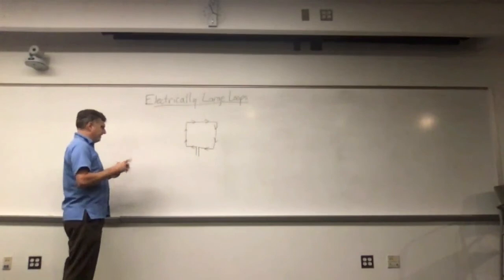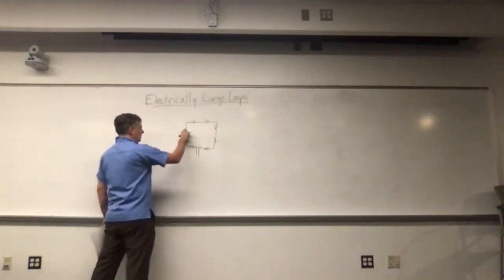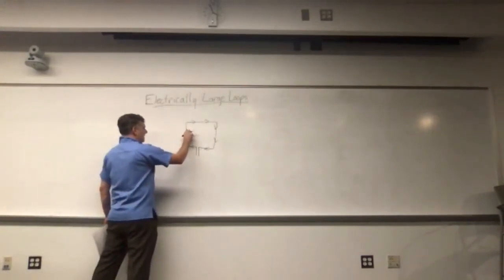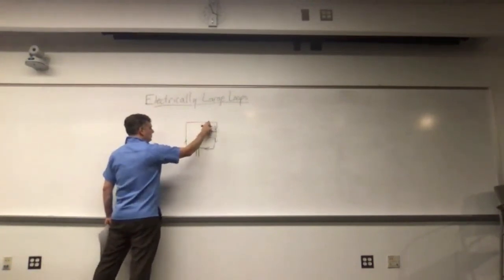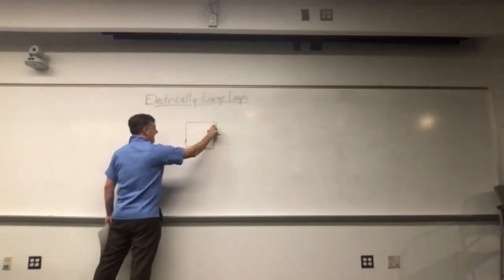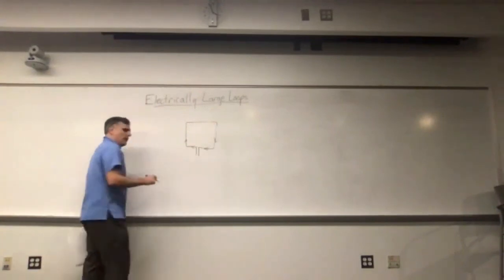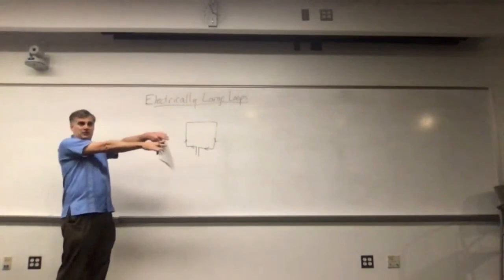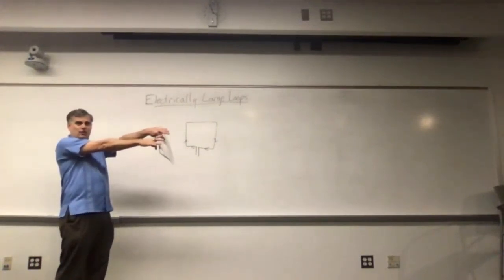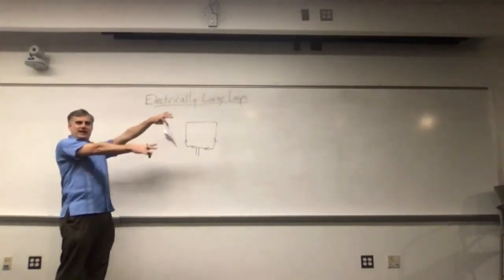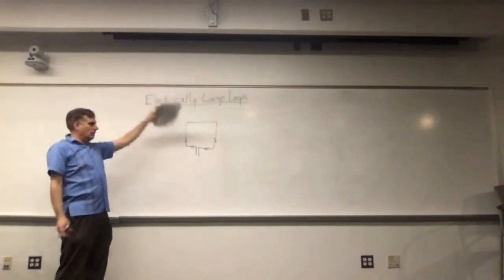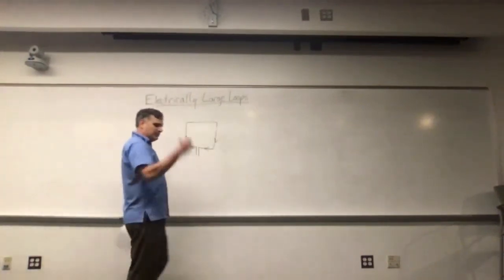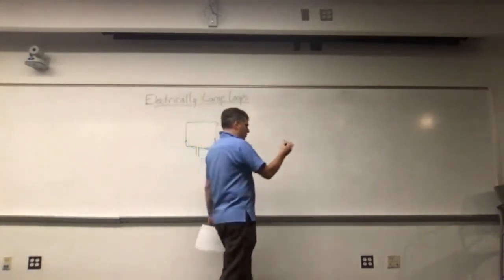Now, in fact, I've drawn this a little bit wrong, because the same technique that we use to calculate the standing waves for dipole antennas applies. Remember at the beginning of the class we had open circuited transmission lines. We figured out what the standing wave pattern would be and we bent them back. We could do the exact same thing here, but it's going to take a little bit of imagination.